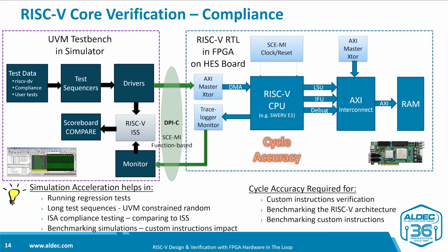And here you can develop your own sequence generators or take advantage of the open source project RISC-V DV. Fixed test sequences can also be accommodated in such a UVM test bench, which is useful when running RISC-V standard compliance test programs.